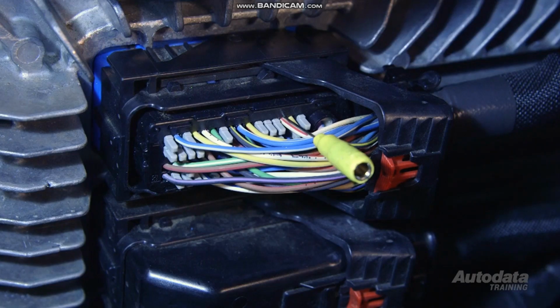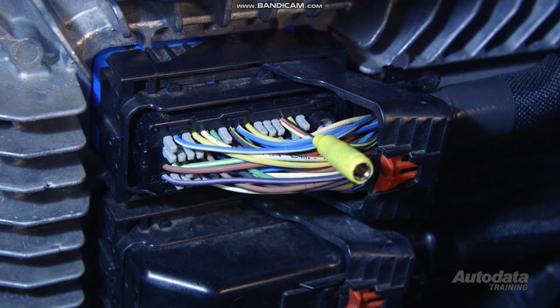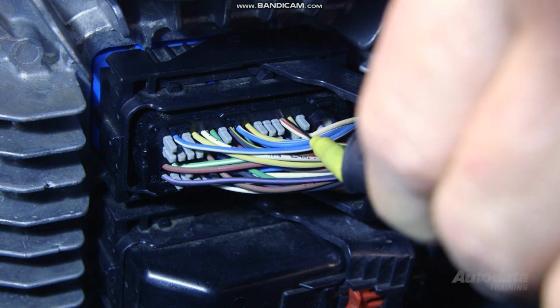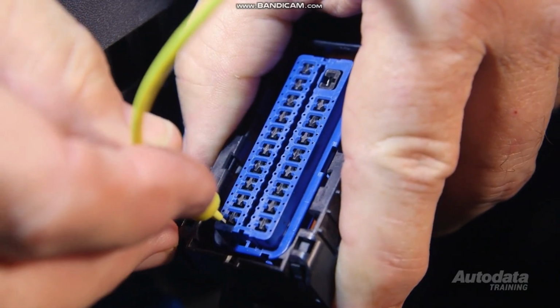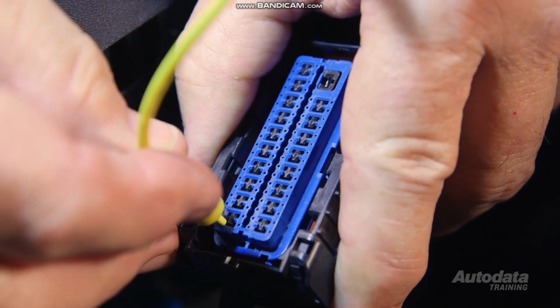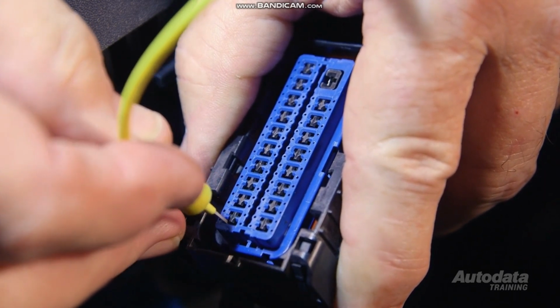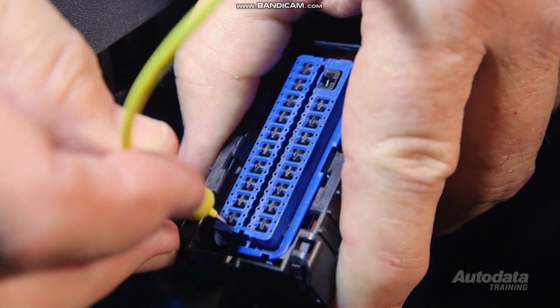If there is no voltage change, turn off the engine, backprobe the module and retest. Voltage here would indicate an open circuit to the actuator. If there is still no voltage, then test the connector for terminal tension and corrosion. The module will be at fault if no problem is found with the terminal.